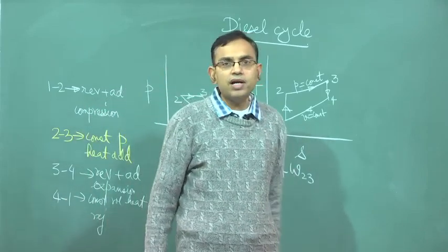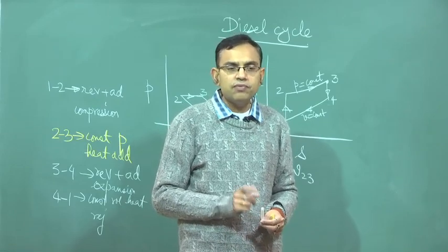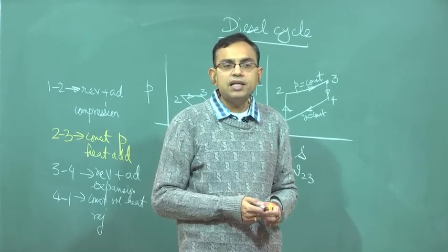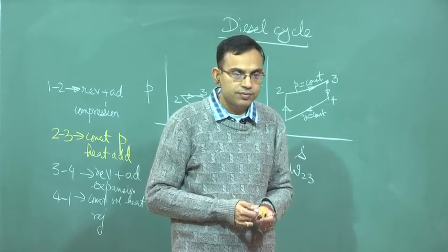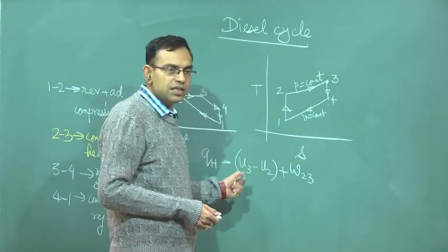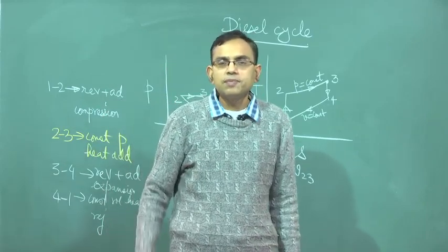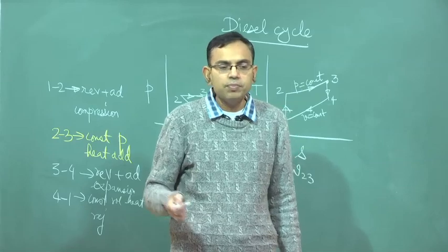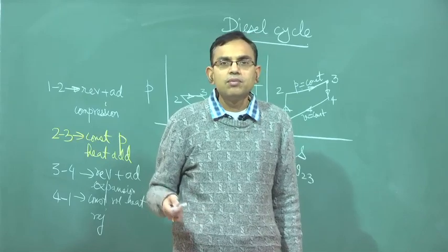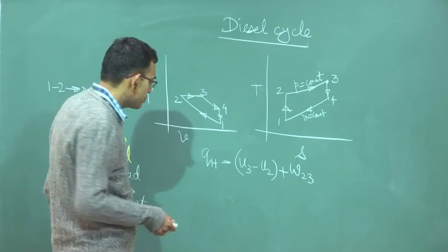One of the major assumptions in the air standard cycle, which in the previous lecture I forgot to mention, but you also add it, is that you neglect changes in kinetic energy and potential energy of the working fluid, because we are writing these expressions neglecting those changes, although that is not what we explicitly tell always. For thermodynamic purposes, the thermal energy contribution is usually much more significant than the kinetic and potential energy contribution.